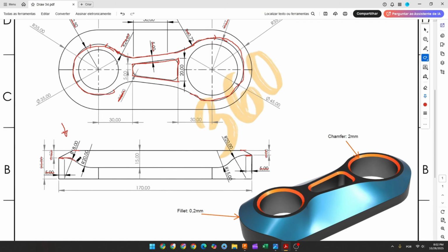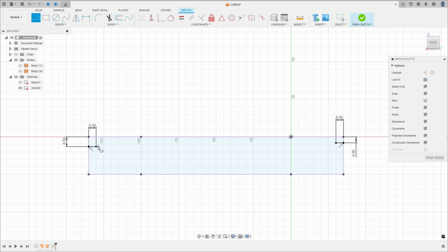Now we'll create an arc here, and another arc, two arcs here, okay? And create this line, and more two arcs here. We'll put the dimensions later, okay? The distance between this line and this one is 15 millimeters. So select line, click with the left button here and hold this. We'll make an arc, okay? Click at this point again, hold the left button of the mouse and make a line here. Okay. Go to sketch dimension, the distance here, 15 millimeters.